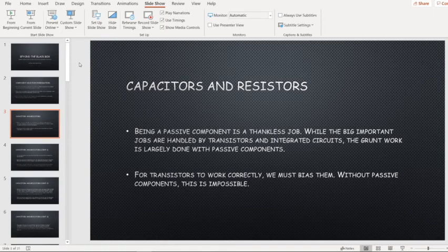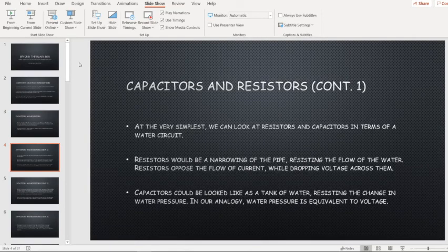So, like, if you're creating an amplifier or something like that, you need to have the correct values of resistors. Like if you're using a bipolar transistor, you need to set a certain current for the base emitter junction to conduct current, which will allow the collector emitter junction to conduct. So when you're using these kind of components, you have to be careful about the types of components you're using. And as I said, we'll get into that more. Next slide, waiting for it to catch up.